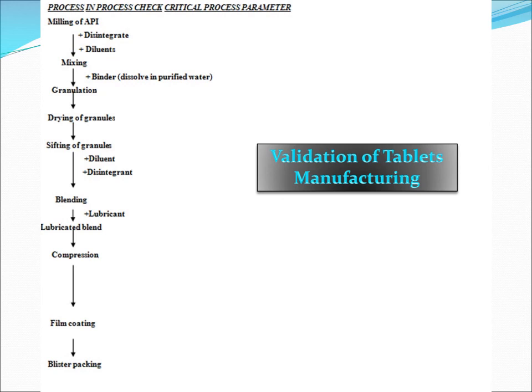You know, for any tablet, you need first to take the active pharmaceutical ingredient, API, and make grinding and add some of the excipients, like disintegrant and diluent, for example, and make mixing, and then add binder and make granulation. Drying of the granules, if there is a wet granulation method, so you need drying, and then sieving or sifting of the granules, allowing them to pass through a sieve, so the big granules will be kept on the sieve and the small powder will escape, and then add the remaining